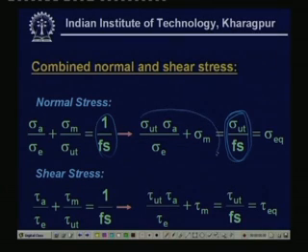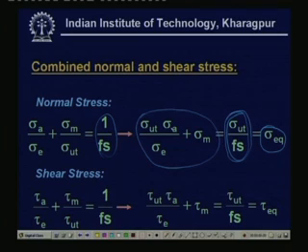So, once it is the concept of the design stress, why not call this entire part of the equation a stress which could be read as sigma equivalent, that is, sigma ultimate divided by factor of safety. In static design we consider this to be a working stress, and in a similar manner for fatigue design we consider sigma ultimate times stress amplitude by sigma E plus sigma m to be a sigma equivalent stress.